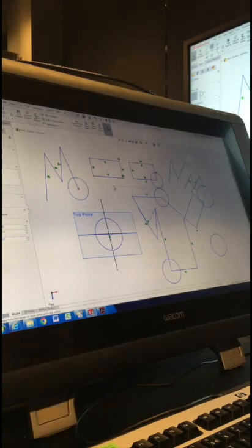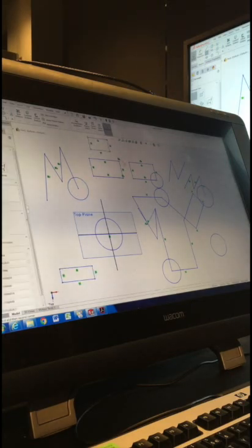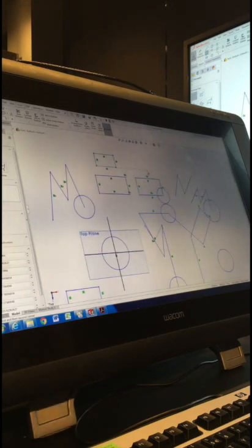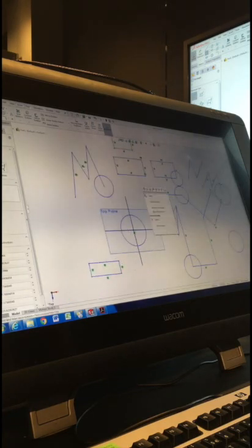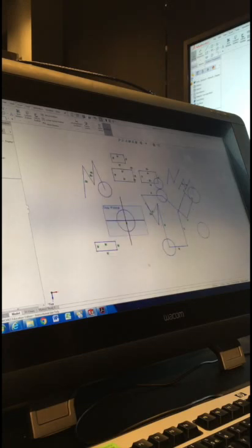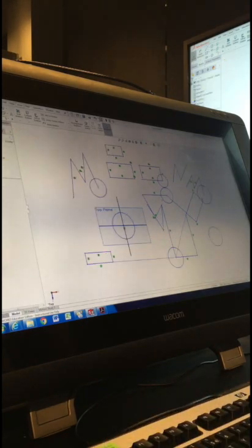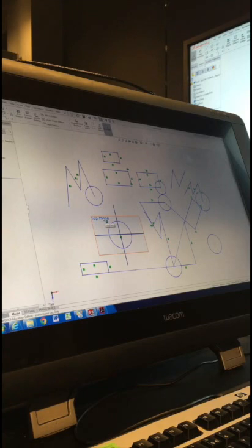Now, the last gesture option is right click, go down, and that is a rectangle. Pretty self-explanatory. When you do the rectangle, it'll add 2 horizontal lines and 2 vertical lines. Okay. So, cool, pretty straightforward. They're just some of the basics. There's a lot of other sketch tools. Okay, 3-point arcs, polygons, slots, spline tool, ellipse, etc. We'll get to those later. I just want to show the basics now to get an understanding of how some of these things work.